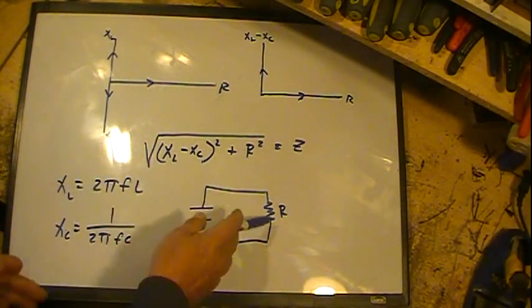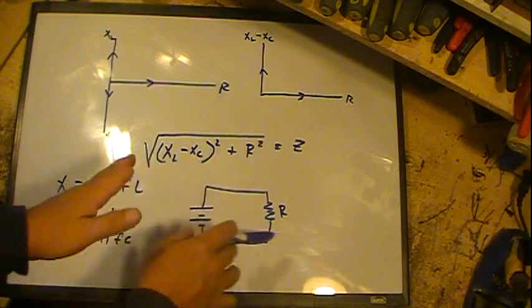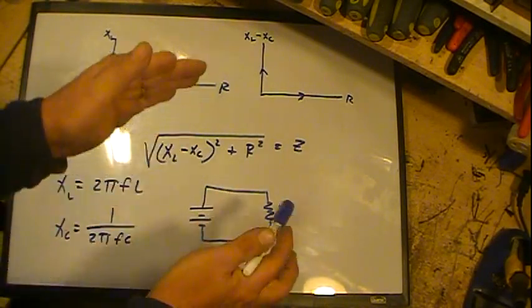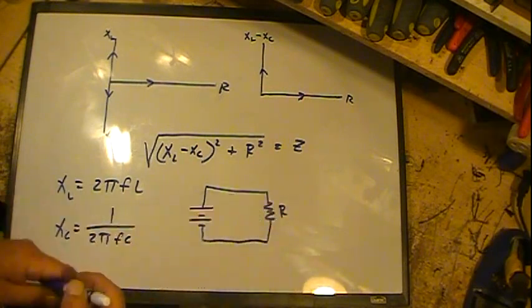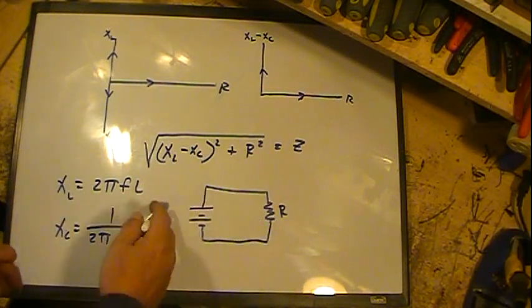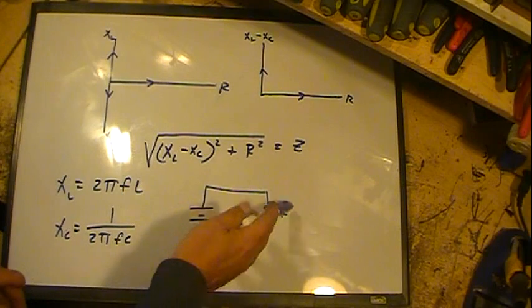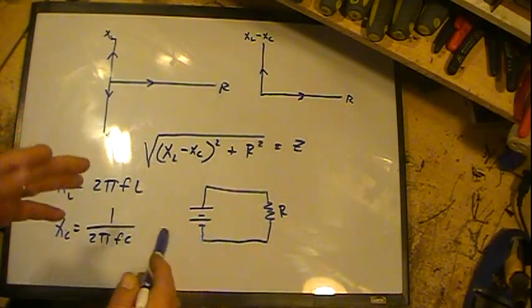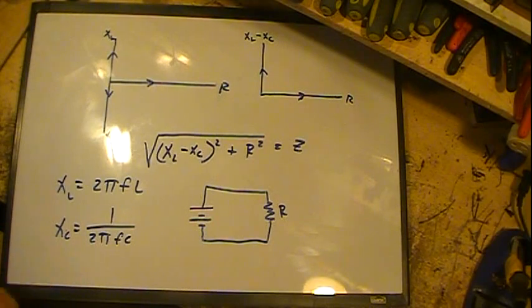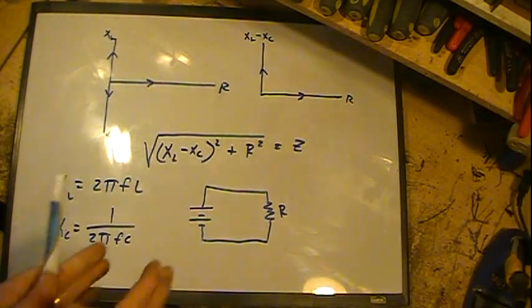Simple circuit. No matter what combinations of resistors you have, you can work them out and bring them down to just a single resistance. And then you have just a single voltage source, single resistance. Use Ohm's law. You can find the current. You can find whatever you need to find in that circuit. That's real simple.